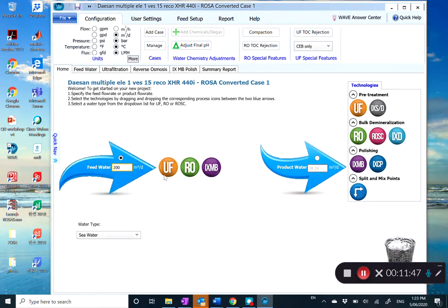We already studied the basic sand filtration design in block 2, so you can design based on that. Also ultrafiltration, membrane bioreactor, or some simple membrane ultrafiltration process can be used for pretreatment. In this case, you can use ultrafiltration.